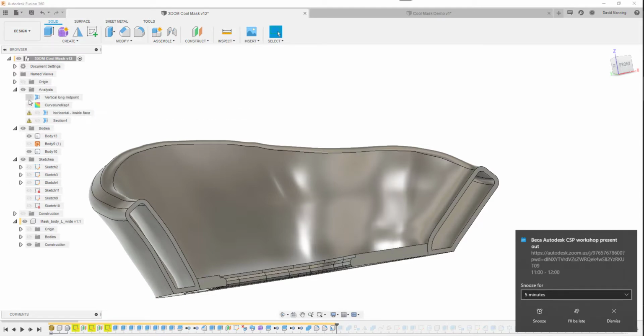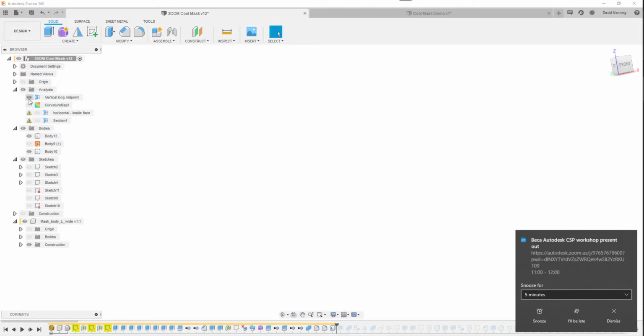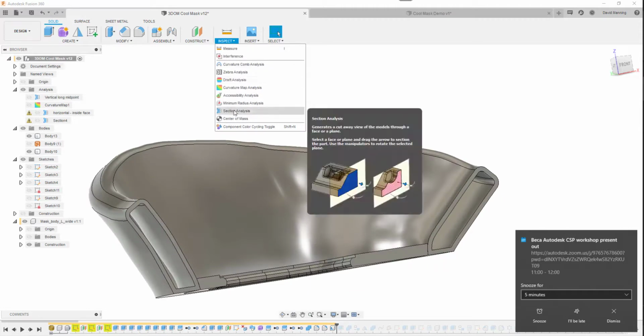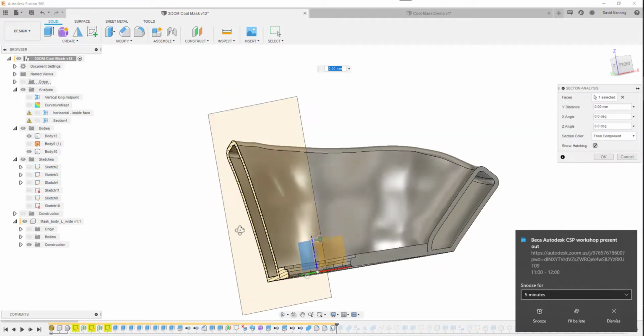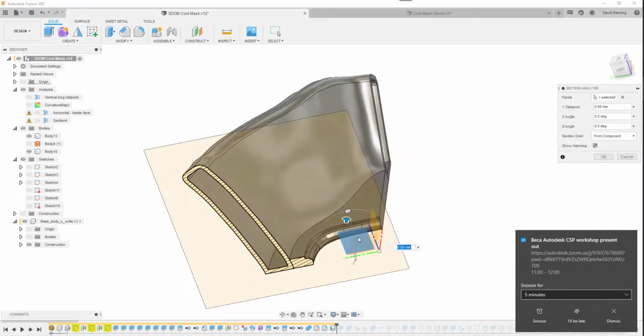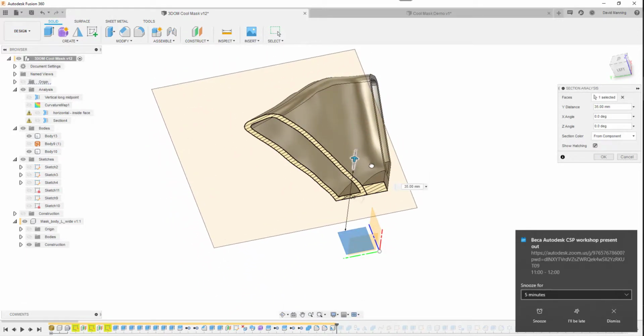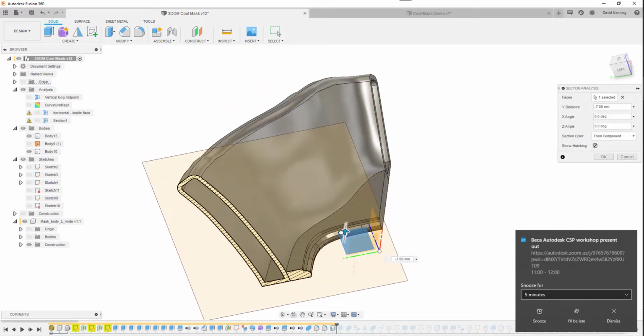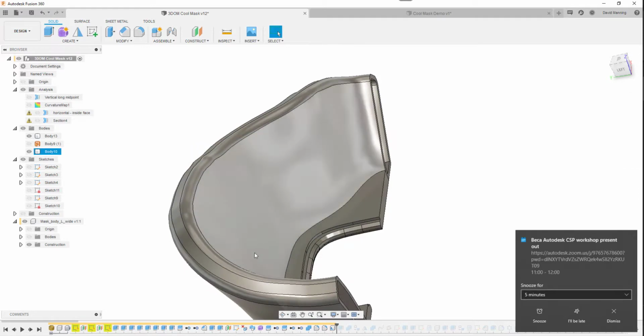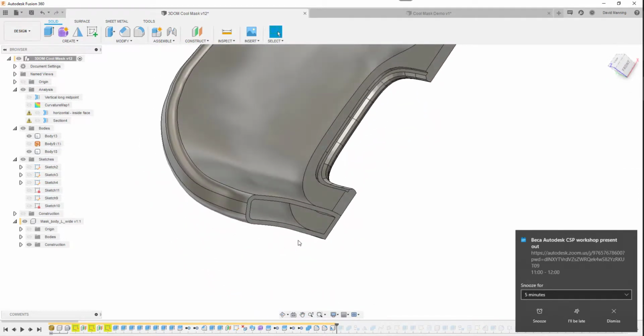hollow entity. Can I trim that? Let's not do that. Let's just do a new inspection section through there, and you can see hollow all the way through. So that can then be filled when we're ready, and it's nice and consistent right through the surfaces. So we know we've got 1.5mm through every single aspect.